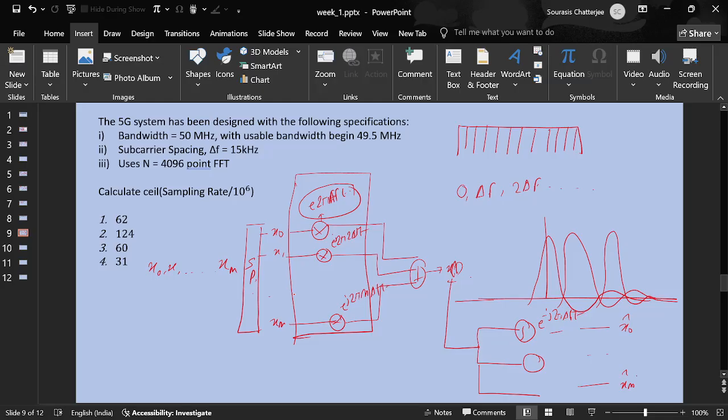So let's say, in a practical system where I am implementing this OFDM transceiver, the cell coverage is pretty big, I mean 2 kilometers or more. Do you think I should be more cautious about this inter-symbol interference or less cautious? More cautious. Your delay spread will be more. Okay, thank you.